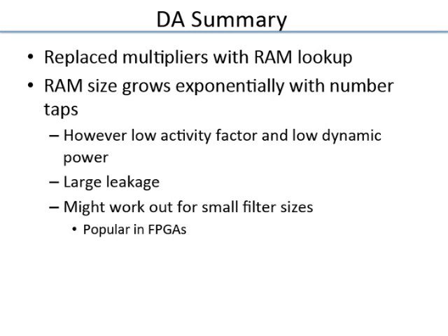For chips also, some people have tried, and up to a certain sized filter, they find it to be more energy efficient to take this approach versus the standard approach. Not necessarily. Again, it depends on the size you have of the memory. So for smaller sizes, this will have benefit over the multiplier. But for larger sizes, the exponential growth of the SRAM will basically give it to the multiplier.